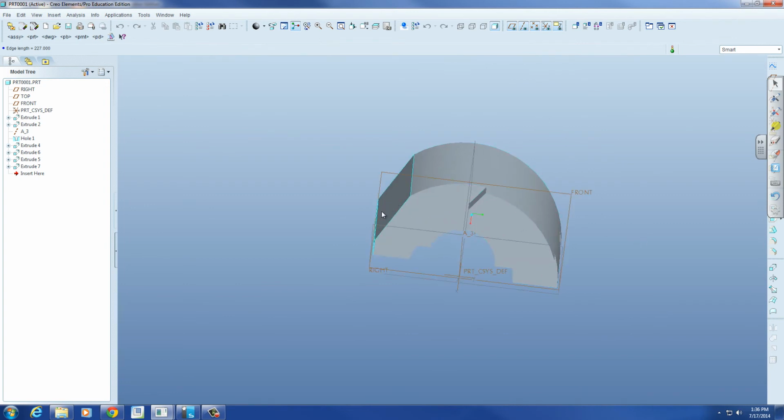So we're going to have to remove this face as well. Not knowing where these go, but then we can replace these faces if they need to be surfaces that are holding something or running surfaces with ribs. That stiffens a part and it gives it a mating surface. It's just not solid. So now we're going to look at coring this part out.